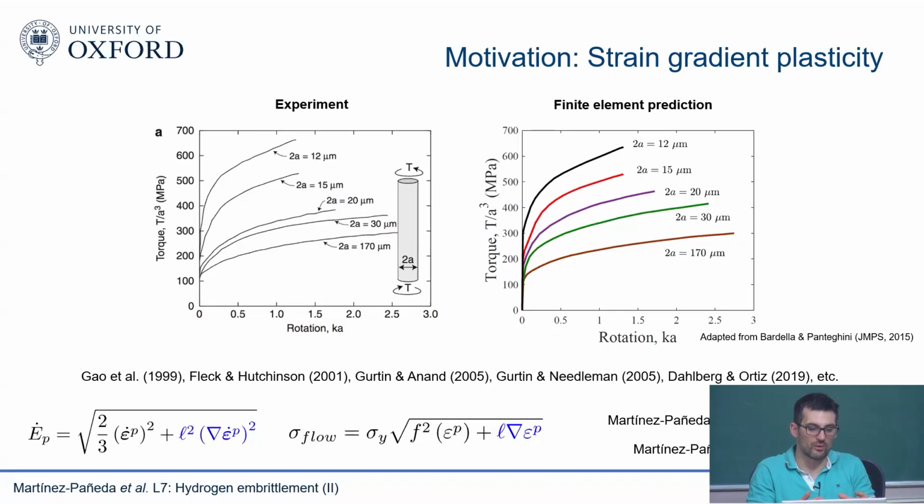I will tell you how, at the microscale, or when gradients are large relative to your sample size, hardening behavior will occur due to these locations, these GNDs. That's the idea. So that's a constant, right, for a given material? Yes, exactly. Once you fit those curves, then irrespective of what size of model I take to load, that remains constant.